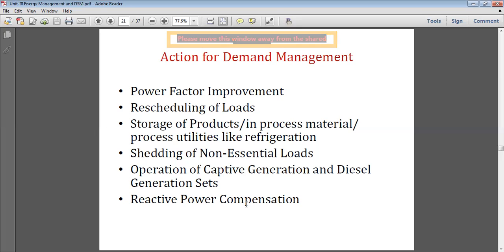So as your maximum demand is going to occur only for one hour, why pay more money on the electricity bill only for one hour in a day? So we can start our DG set. We can shift some part of the load to the DG set, and once our maximum demand decreases, we will switch off the generating unit, that is our generator DG set, and again shift to our regular grid power supply. By this way, we are able to reduce the maximum demand.